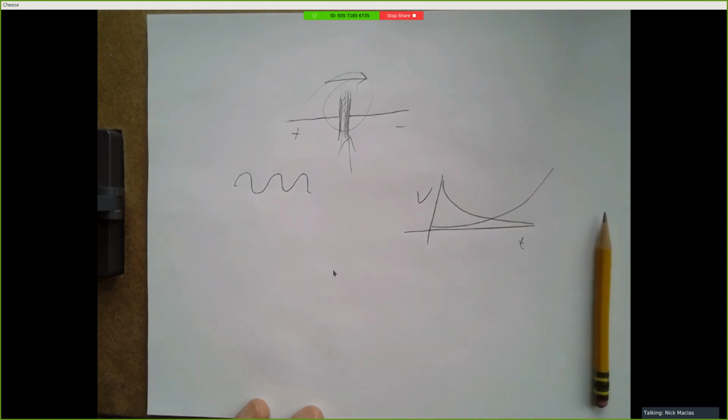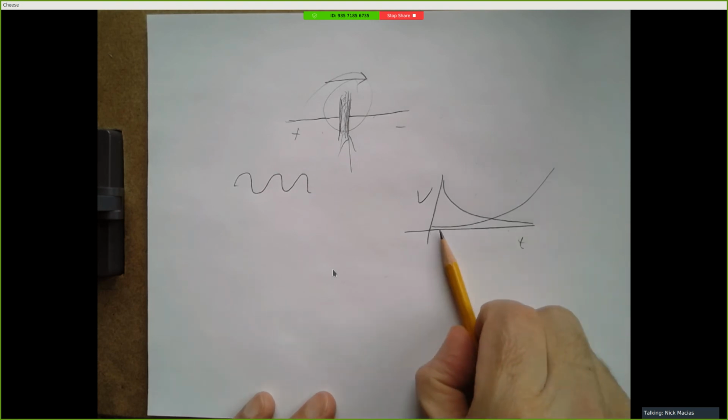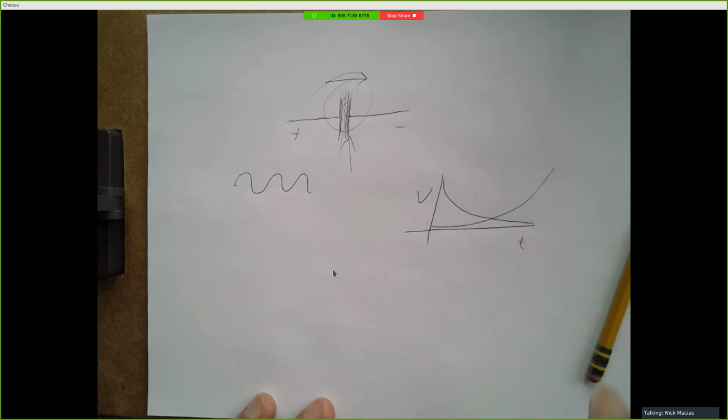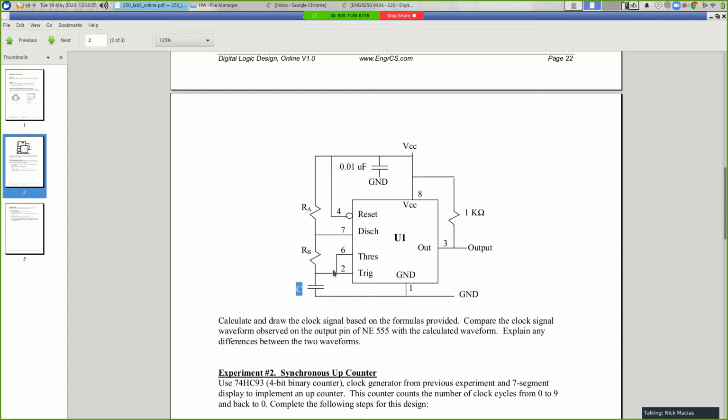So that you might close a switch and instead of the output immediately going to 5 volts, it slowly rises over, say, half a second. And it's that ability to slowly change voltage as an exponential function that lets this and the circuitry in here oscillate. Okay. So could a capacitor be used to prevent damage to components inside by storing the excess charge when connected to ground? Yep, exactly.